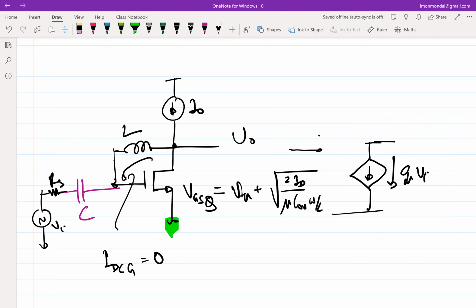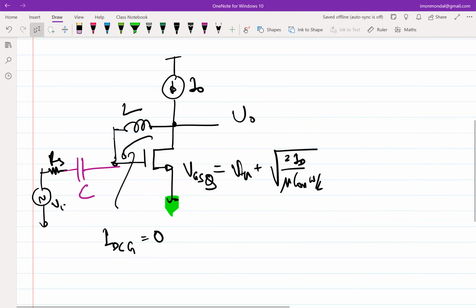You should always keep this in your back pocket. Okay, fine. So your VG has been set up using this, and this clearly brings out the fact that if you want large I0, your VGS will be higher and so on. But at least it has to be threshold voltage or more.